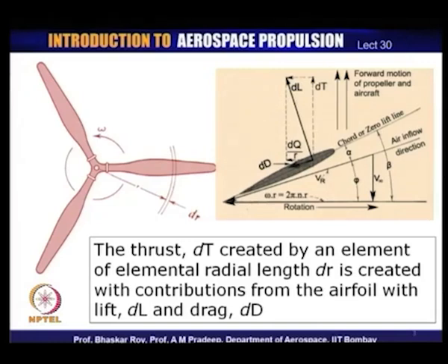So, you have here the propeller blade section being typically harnessed on the one hand using the CL/CD characteristics, on the other hand aligning it to the actual propeller operation in terms of rotation and its forward velocity.